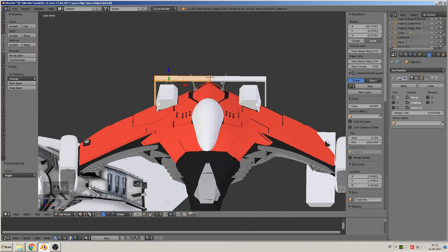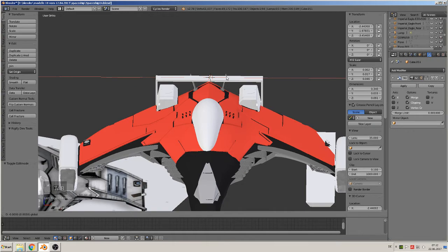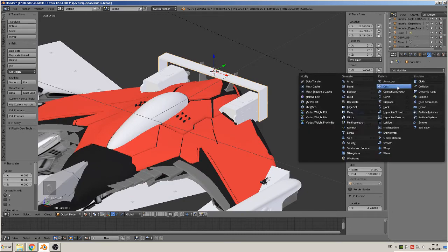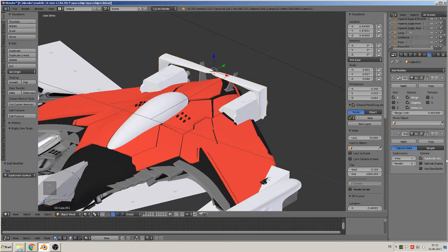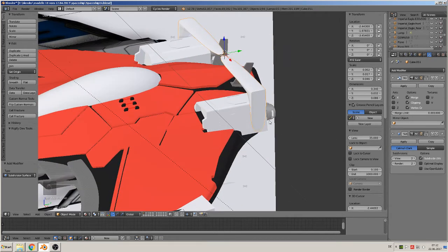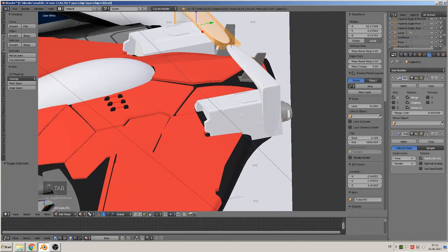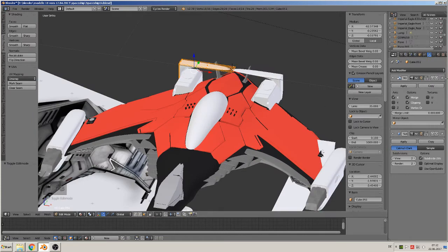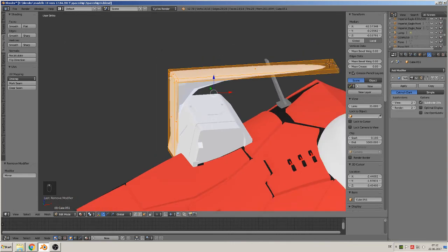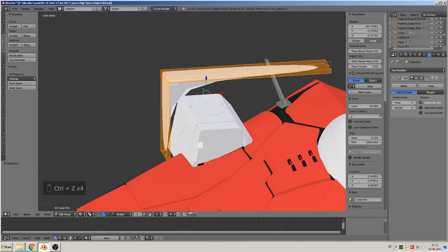So with clipping and merging on, we can bring that more together. So that is that. We will have subdivision surface on it, level 2. And I make it without a mirror. I see that gives problems. And we will need here another proportion. So that means we go back.